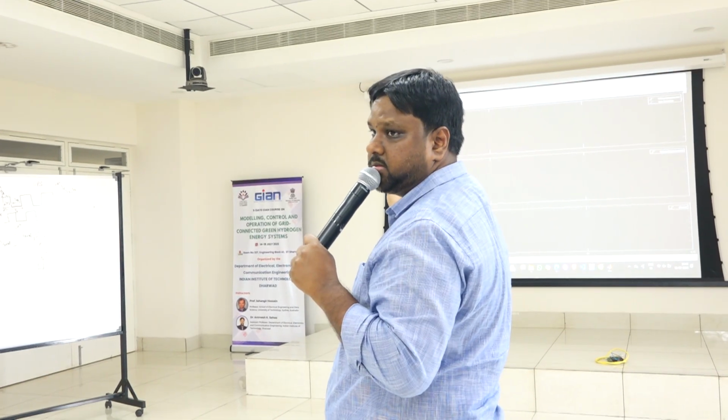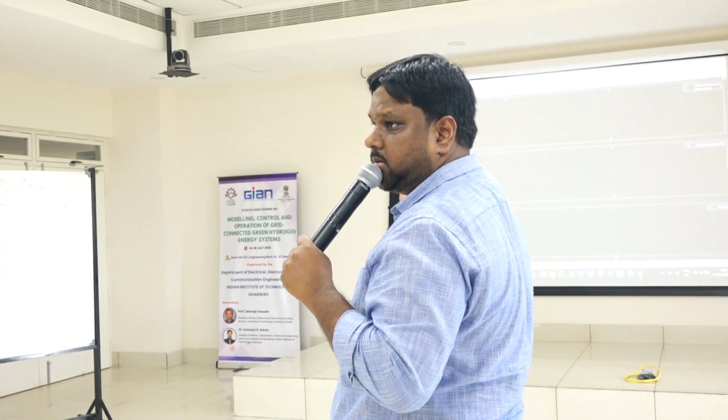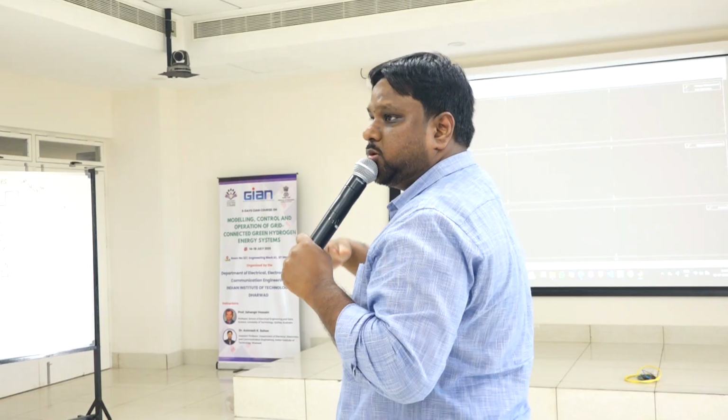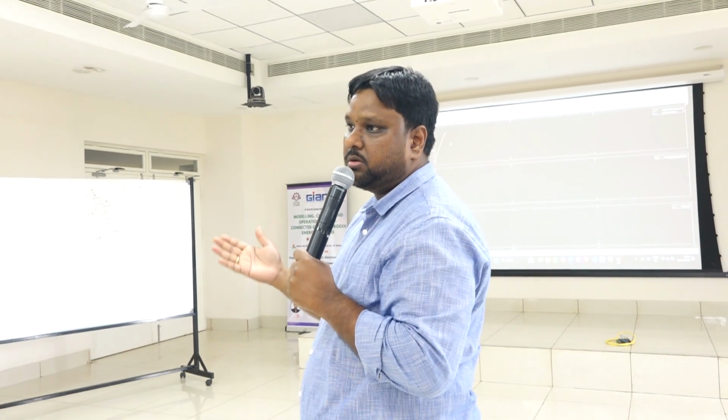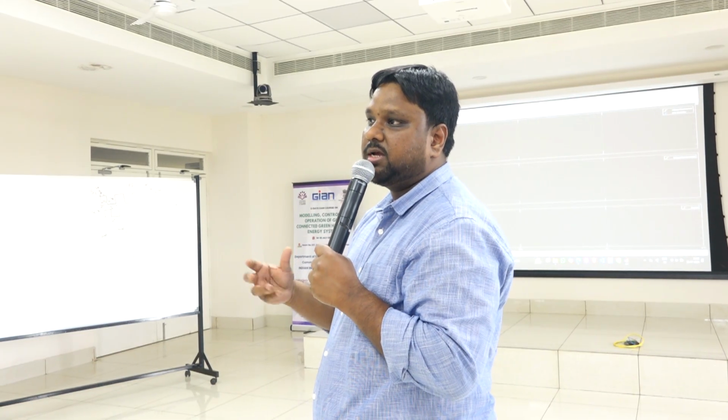But again, making it too finely tuned, too tight, to make it follow very fast, sometimes the system gets unstable. So there you have to have some theoretical background on the range you can select those parameters from.